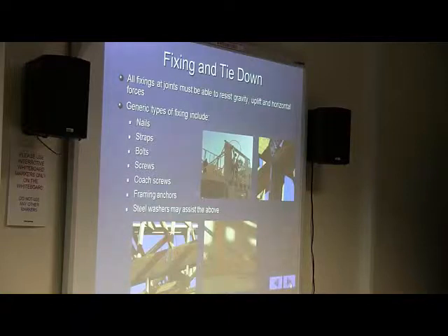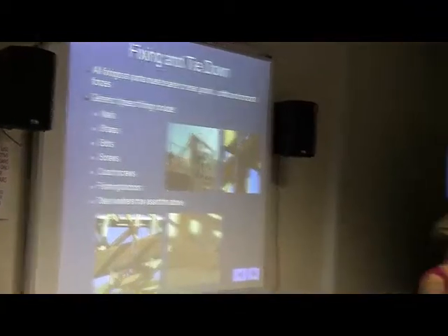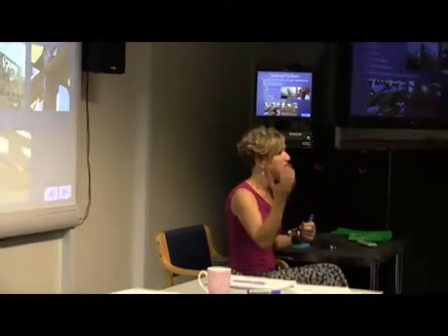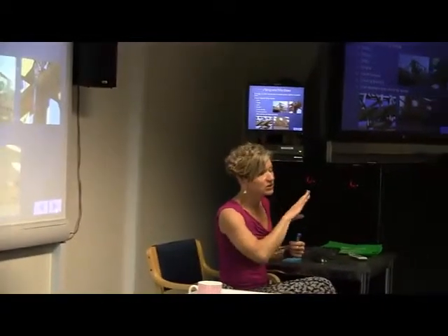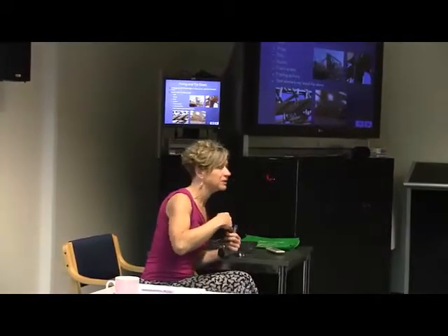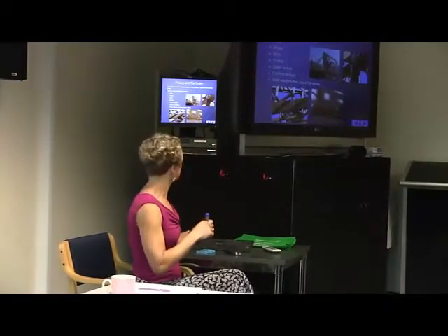So to have a look at some bracing and the fixings, putting bracing panels into the walls is not sufficient because think back to those different situations where you've got overturning. Okay, so lateral loads on the side of a building can also cause an uplift sort of effect, can lift the floor of the building.